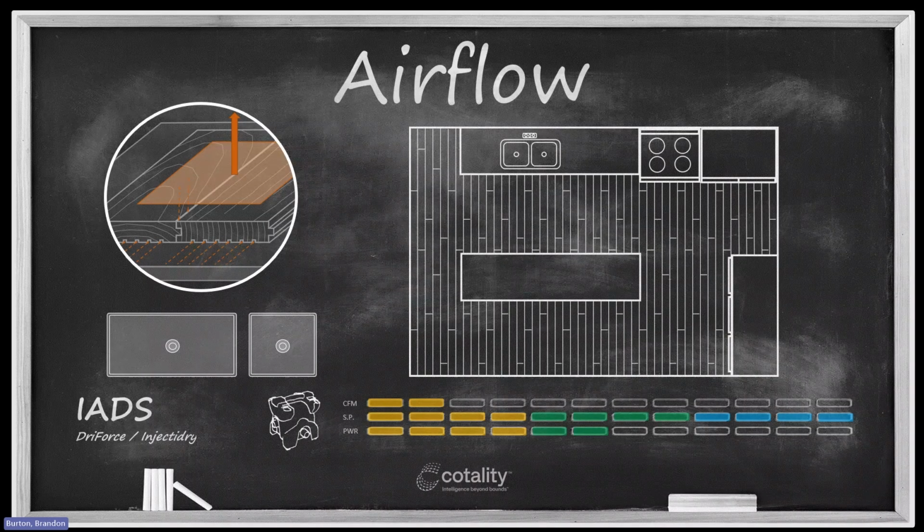The flutes are an area underneath the hardwood that has been milled out. So we have a little bit of a recessed area there. And the intent behind those flutes is to put less of the hardwood in contact with the substrate. So when there's moisture transfer, there is less wood that is expanding and contracting and less dimensional change. That's the reason for the flutes that are on the bottom.